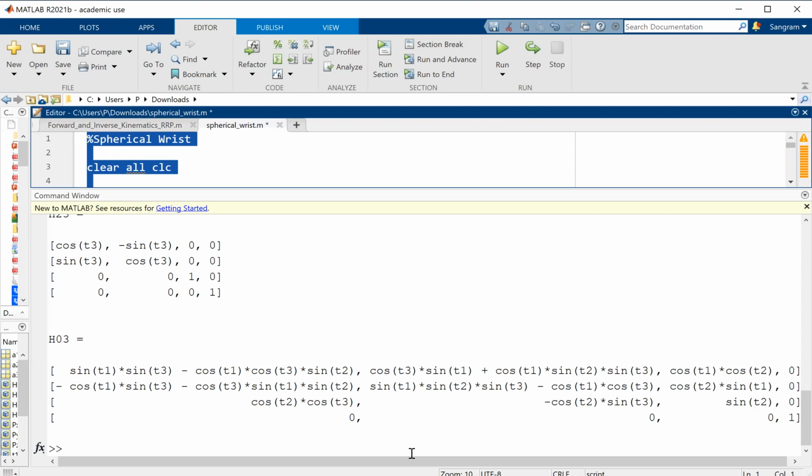I want you to understand, if you use that approach, you cannot have orientation calculated separately, because your theta 1, theta 2, theta 3 for the end effector positions are fixed, which means those theta 1, theta 2, theta 3 need to go here, and that will dictate the orientation of the end effector. But that is not the purpose of the spherical wrist. Spherical wrist primarily is used for the orientation and not position. Do you agree with me?